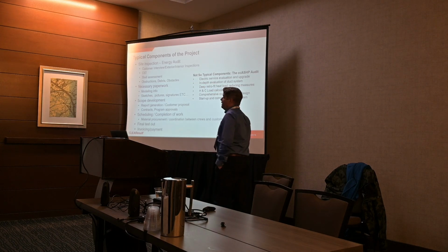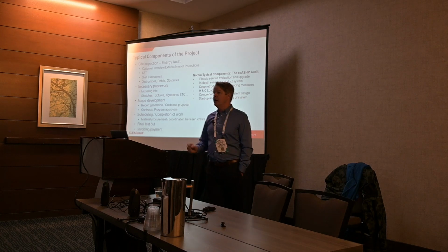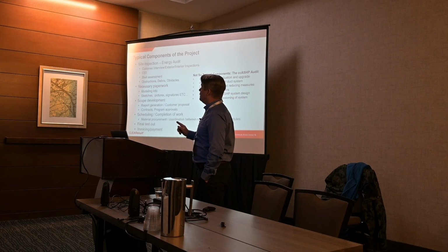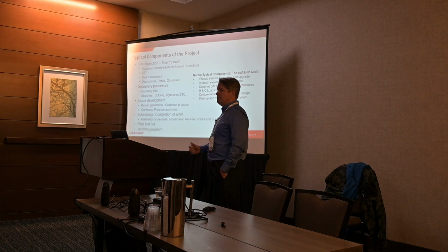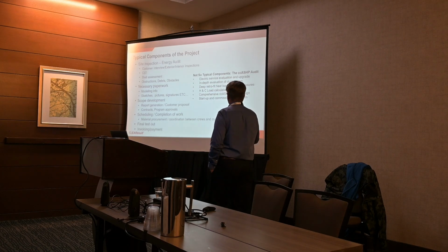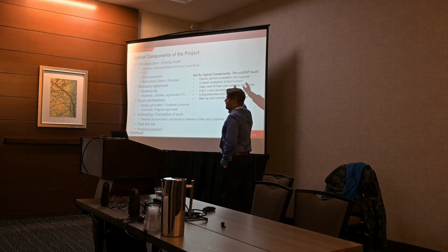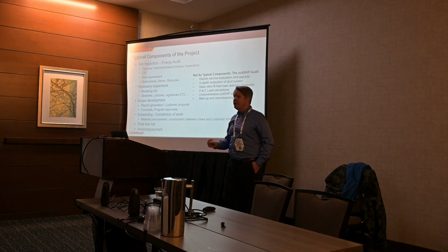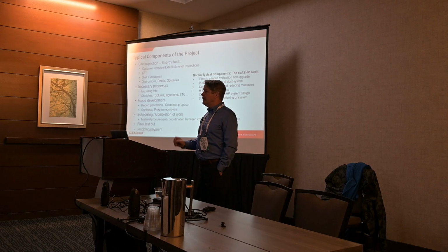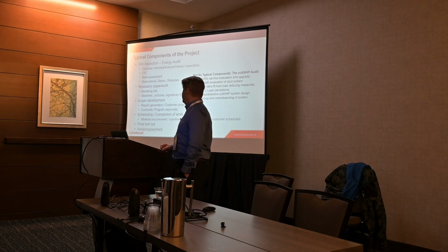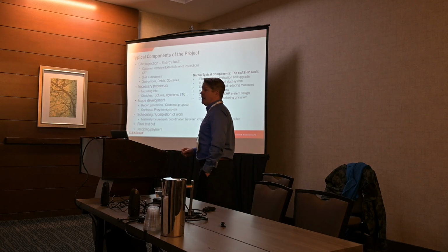We do an in-depth evaluation of the duct system, okay, if it has one. It's a duct system. It's got R6 on it. Good to go, let's go, right? That won't fly anymore. We need to know that this duct system can deliver the amount of air to the space at the temperature we need in order to condition that space. If it can't, or we don't think it can, we have to fix it. We can't just hope for the best, okay?